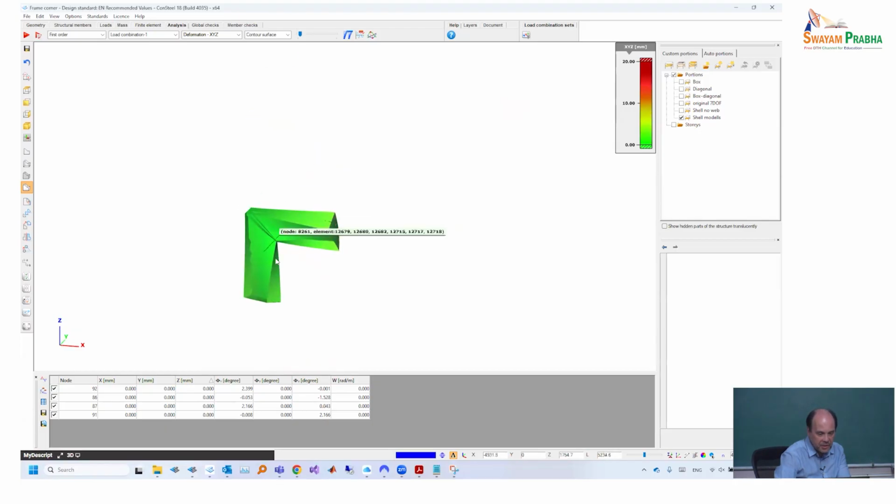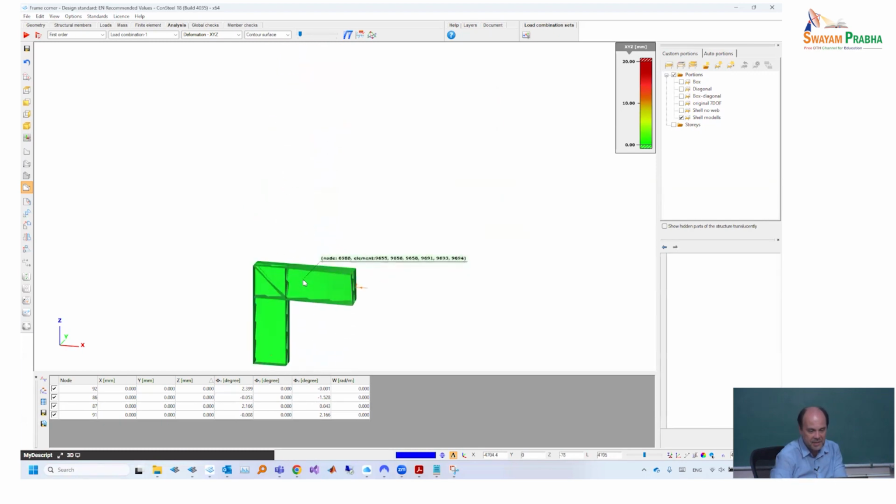So here the behavior is a bit more similar to a beam, because I stopped the serious deformation of a section by placing here in this turning cross-section a strong stiffener, and that's the reason that this deformation is more similar to what the beam element by itself would try to do without any information about the connection. And this is extremely important.